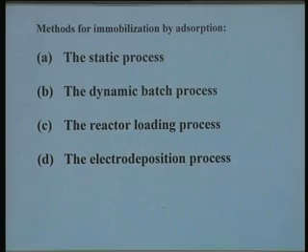Now practically for adsorption, essentially we follow a number of methods; at least 4 major methods are used in practice. The first and probably the most trivial method is the static process. That means essentially that you bring an enzyme solution in contact with a carrier and leave it overnight or over a long period of time. Adsorption takes place without even agitation.